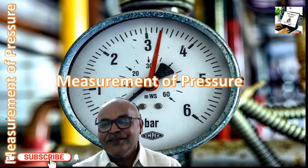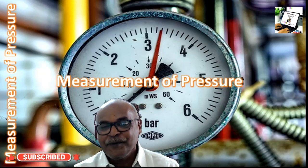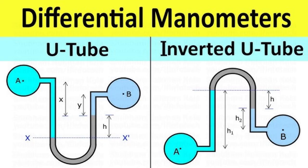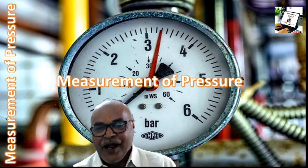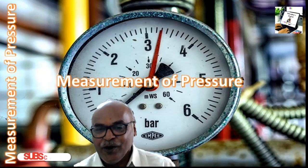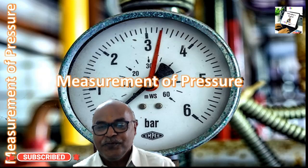And then we studied the differential inverted manometers. So that is PA by W minus PB by W is equal to H dash into S2 upon S1 minus 1. A common example is PA by W minus PB by W is H dash into 13.6 (mercury) upon 1 (that is water) minus 1. So PA by W minus PB by W is equal to 12.6 times H dash.